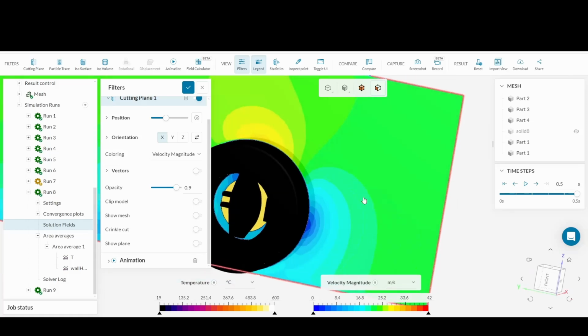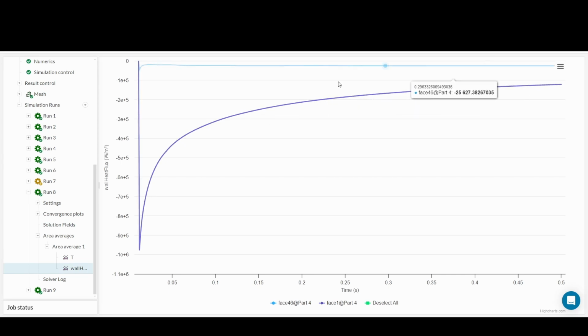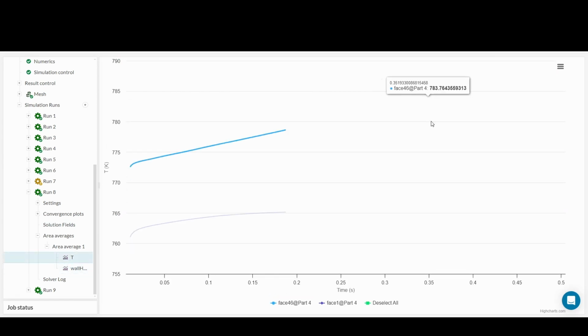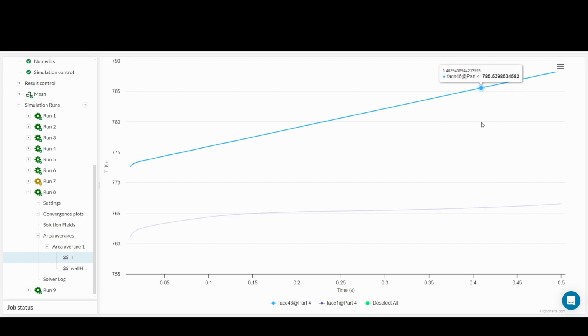So we actually saw different temperatures, different heat flux on each side of the rotor. But I just took the heat flux and the different temperatures and got an average for my simulation just to simplify things. So I got one number, and then as you saw on the spreadsheet, I just used kind of random numbers just to show the difference of front and rear rotors. But you can do this.